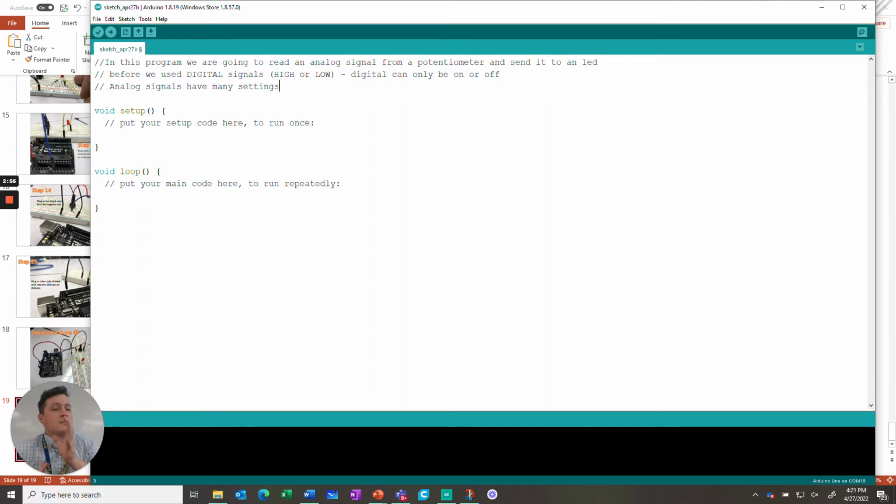But there's lots, so you can be anywhere in a range. It has many settings. We'll just say it's a large range. So you can be anywhere in between. That's how we get the dimness, or the brightness rather, on this thing. Right now it's at 0, but we can turn it up, and we have 255 different settings of brightness that the LED can be at, okay?